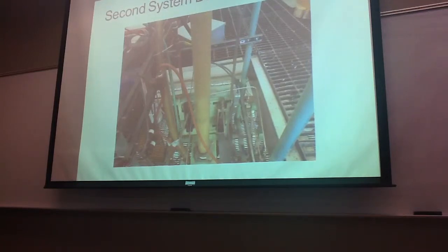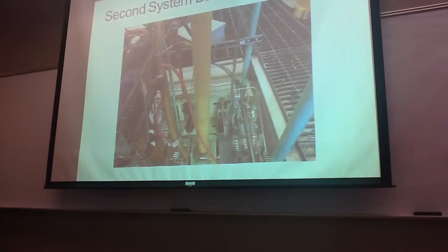But for everyone else, as I'm a chemie and I'm in this system, I will try to explain it to you. So let's say you have a nasty gas, or a gas that's an output of some kind of reactor that has something nasty in it. And that nasty thing just happens to dissolve into water or some other fluid that you have on hand. So how do you get rid of that? Well, you use an absorber airflow system.